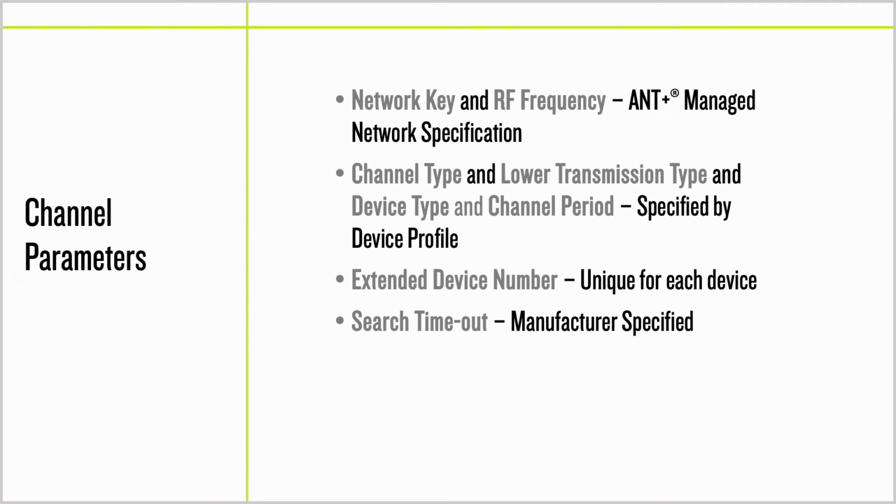We went over all the channel parameters in the ANT crash course. For each ANT+ device profile, a specification exists explaining how to set each parameter. Some parameters are specified by the ANT+ network and are the same across profiles, and others are unique to a specific profile. Others still are unique per device or manufacturer. Care should be taken to understand and set each parameter correctly for each device profile implemented.